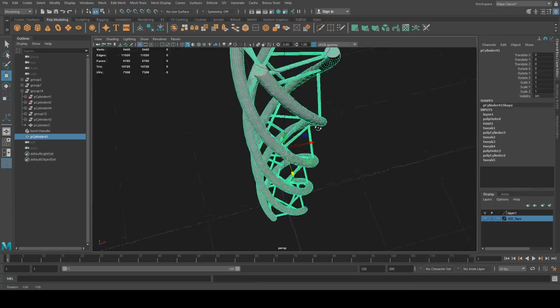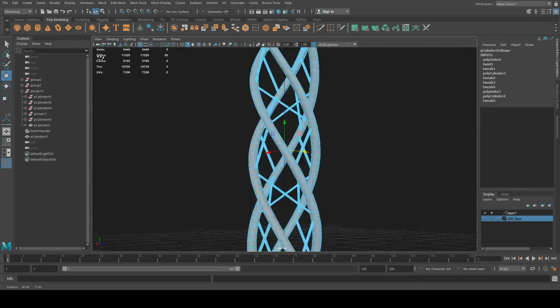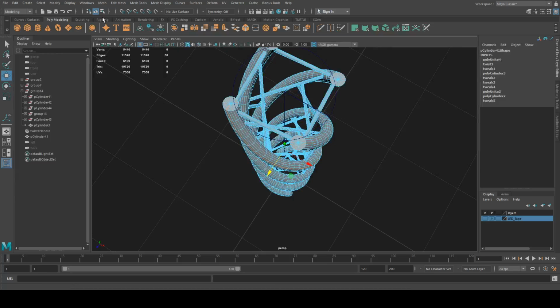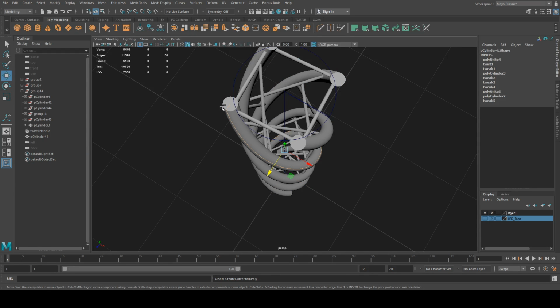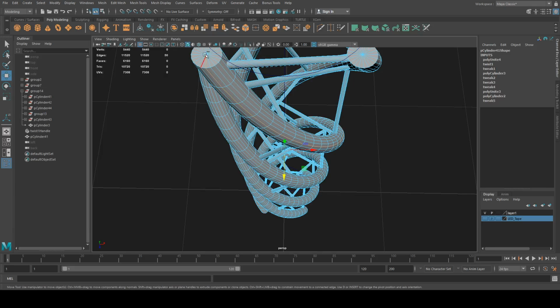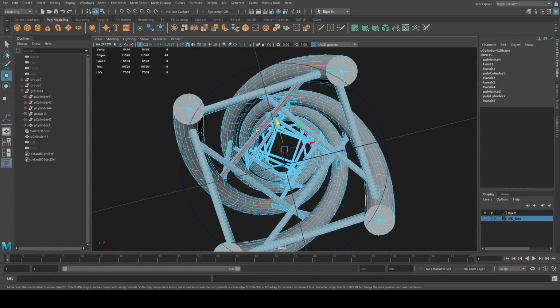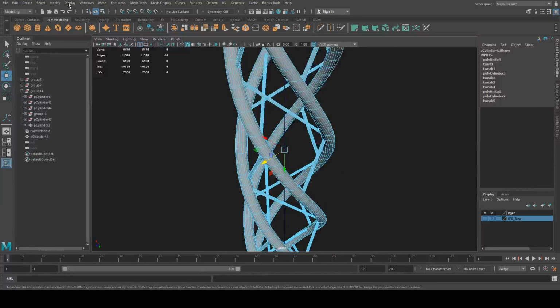On this spiral truss, I am going to grab an edge. It goes all the way around, and I'm going to go to modify, convert here in Maya, and I'm going to change that polygon edge into a curve. Except I don't really want all of that. So let's double click that again, except I don't want you, and I don't want you.